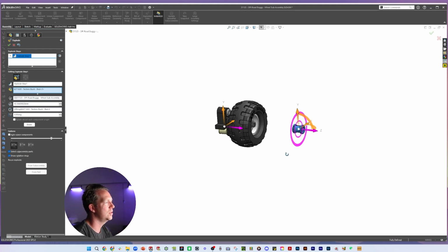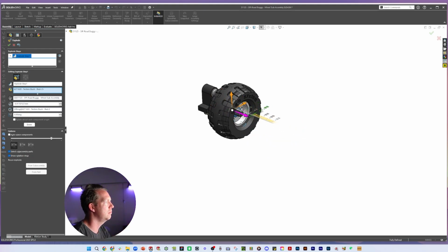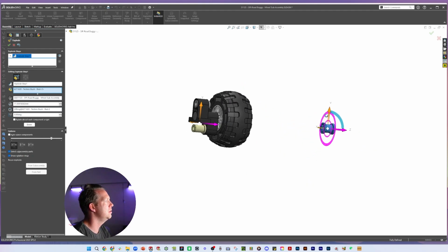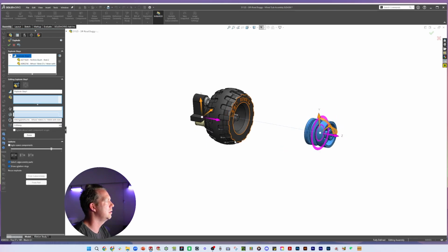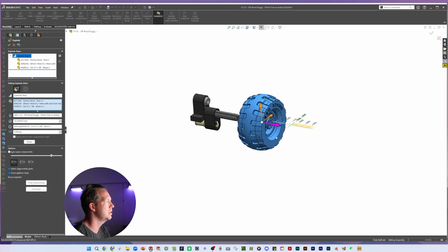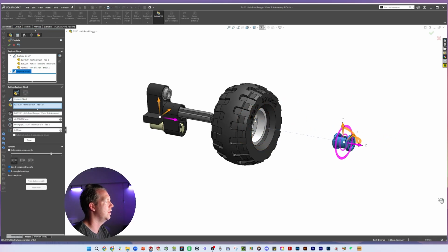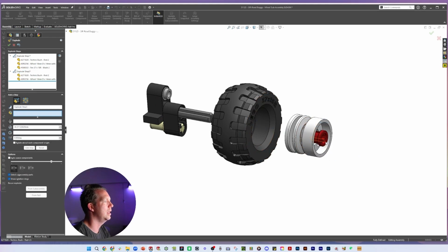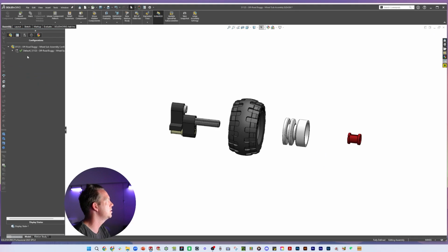Typically when I'm doing exploded views for spacing, you just want to have it so that you can see clearly that part from whatever view you're communicating in your drawings or images. All right, you just don't want it to be like hidden away or inside another part where it should be. Now, sometimes that means you change the order of your explode. So by that, it means that I could actually explode these three at the same time, and then I could take this one out a bit further, or even these two. But then depending on that order, the steps, that's going to impact your animation.